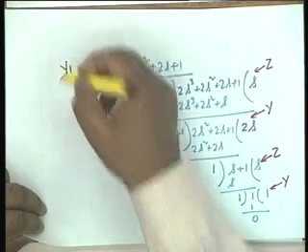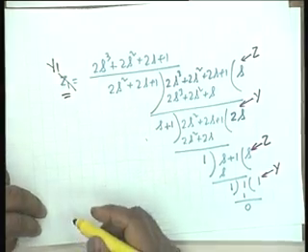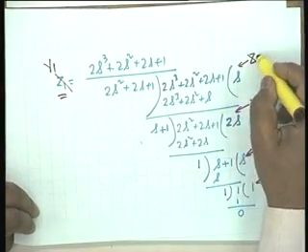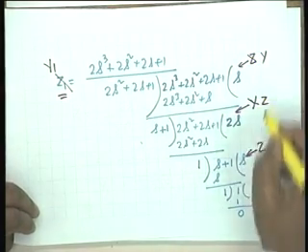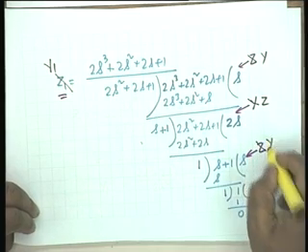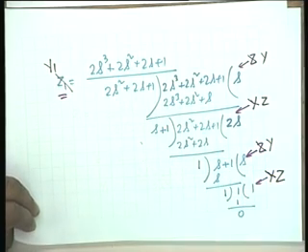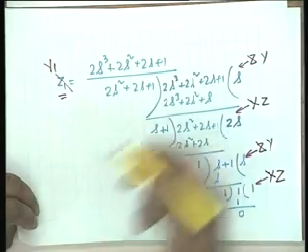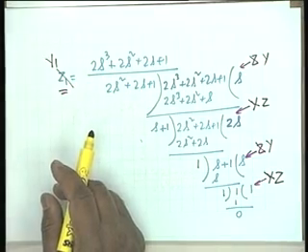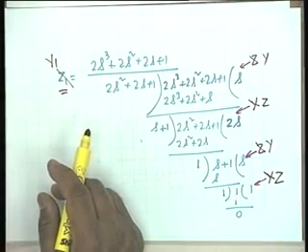If you consider this an admittance, then obviously the first element would be an admittance, second would be an impedance, third would be admittance, and the fourth would be impedance. Is that okay? It is exactly the same continued fraction expansion except that the dimensions change, which means that the network shall now be, instead of starting with a series inductor, I shall have to start with a capacitor of